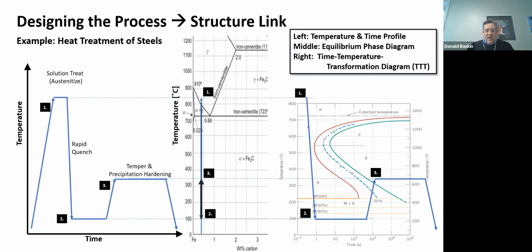So the heat treatment process for steel isn't that much different than what I showed you for aluminum. At room temperature, a non-heat treated steel is this BCC, body center cubic material, with ferrite, for example. When you heat that material up above, say, 850C or 800C, depending on the composition, sometimes 900C, the body center cubic material will transform to a face center cubic material.